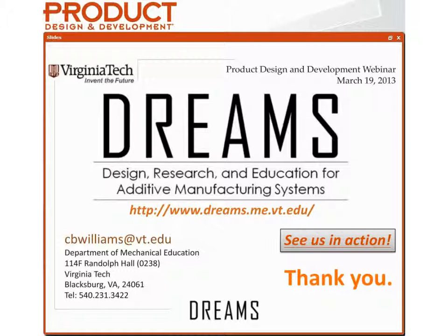Is there any difference in the structural integrity between the 3D printing and machined parts? Sure, I can answer that. And the answer is, yeah, it is. Again, that's something that we've seen in the literature, and especially in the polymers. Again, different technologies are better at it than others. The most common reason is the interlayer bonding in the Z direction.